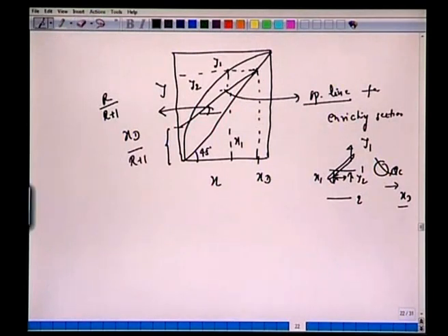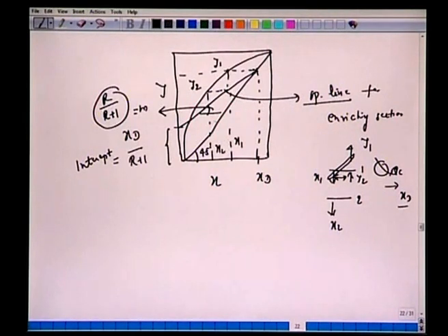Alright, so we have r over r plus 1 as the slope, and the intercept, which is xD over r plus 1. So we have this y2 again. Let's start. This y2 is in equilibrium with this x2. So we have this x2, again this x2, and now we have this y2, and so forth. Starting from this, now we can construct the stages.